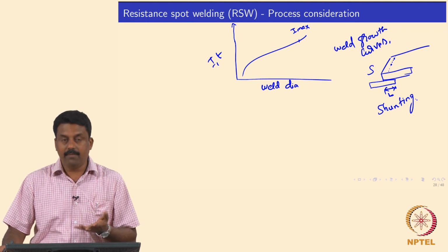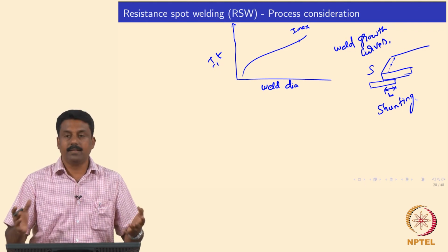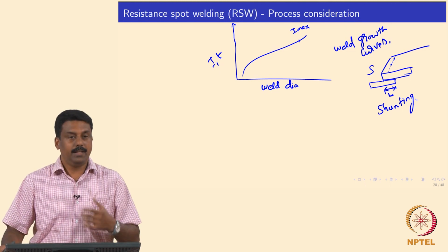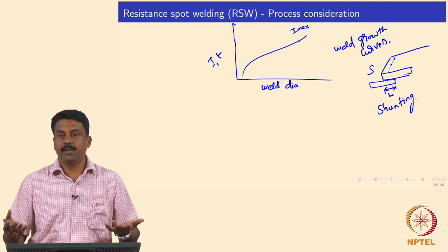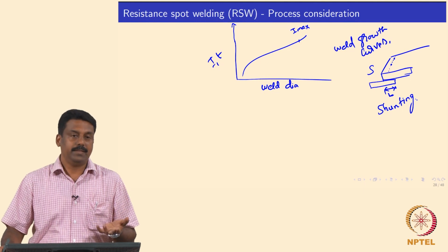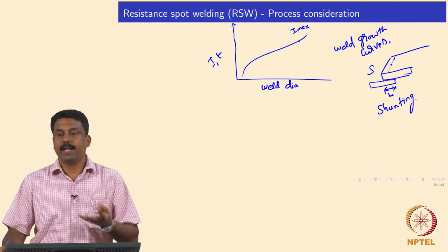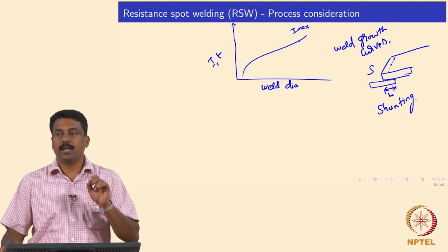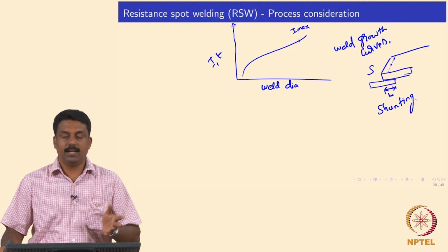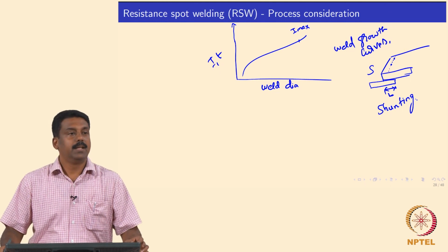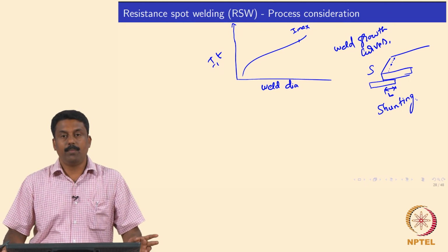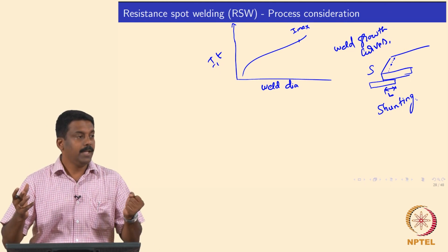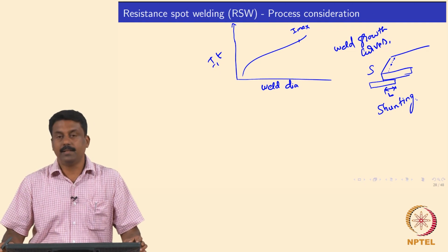So the S and L we can get for varying thicknesses and varying materials, and I showed you a table which you can refer to for common engineering alloys. For a detailed case, if you want to identify what the L and S are, you will have to do a complete structural analysis using FEM. Generally it is done for automotive components. When they conceive the design, they do an elaborate structural analysis, okay.